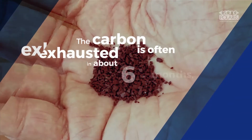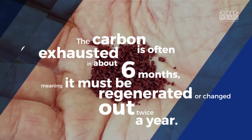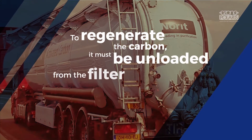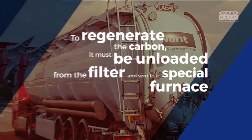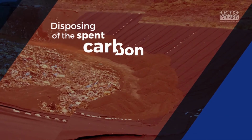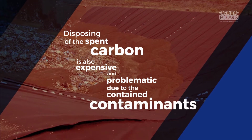The carbon is often exhausted in about 6 months, meaning it must be regenerated or changed out twice a year. To regenerate the carbon, it must be unloaded from the filter and sent to a special furnace, which is almost as expensive as replacing it. Disposing of the spent carbon is also expensive and problematic due to the contained contaminants.